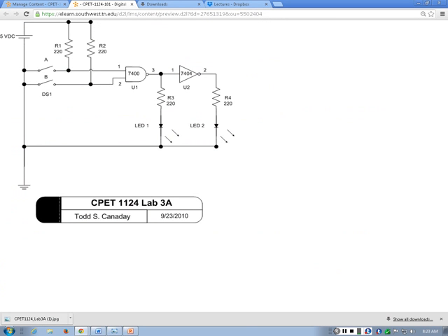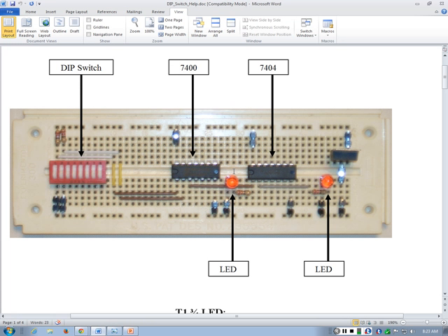You have to connect the top of the switch to the power, basically you are powering up the switch. Because by changing the switch you are giving 1 and 0, but how is that 1 coming? That's a voltage, right? I'm saying logically there is a 1, but technically there is a voltage, and that voltage should be coming from somewhere. So you are connecting the switch to the power, let's say. Okay? So you always have to do that, doesn't matter which switches you want to use. At some point you might have to use all the switches, but not right now.